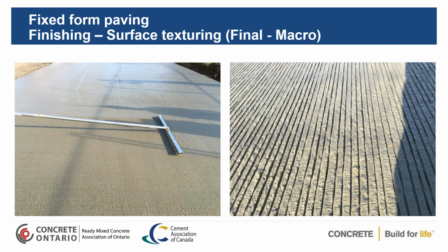And you'll see here on the right-hand side, these are the grooves that you're getting from running over top of the burlap drag area. So you've got your nice surface texture for your micro texture. You're now putting your macro texture in by dragging the broom across it.